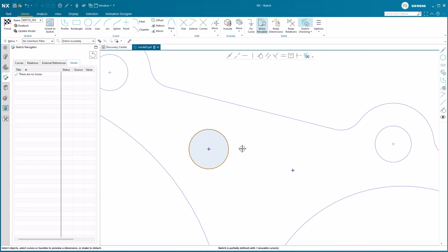We now continue by copying the circle from the inlet to the outlet. We again immediately see the visual issue tag as we missed making it properly concentric. To speed things up where we are really clear on the issue, you can simply double click on the visual tag to correct the issue. So here we simply double click the visual tag and correct the issue.